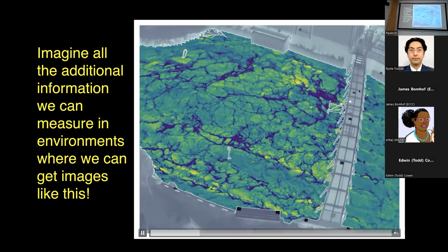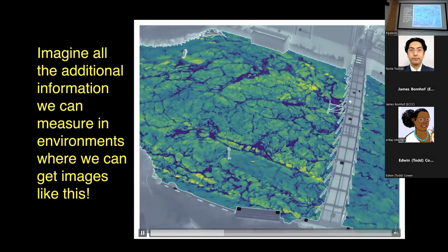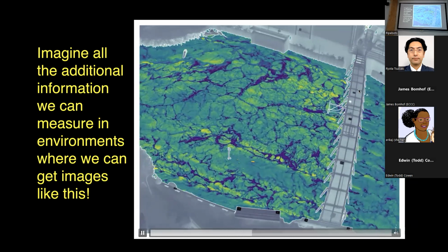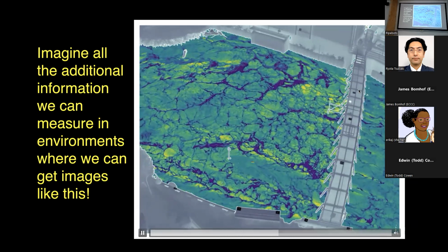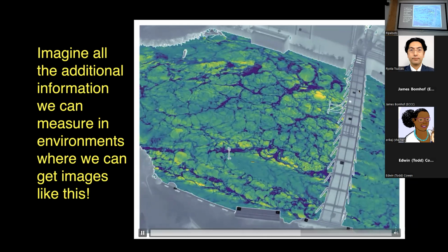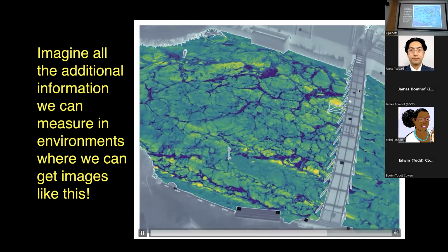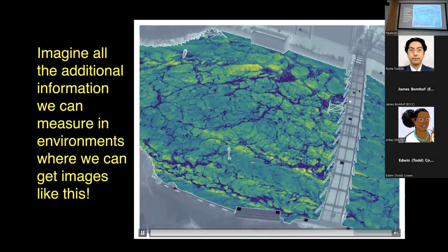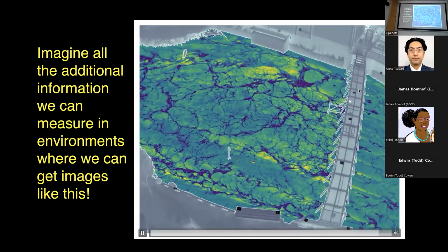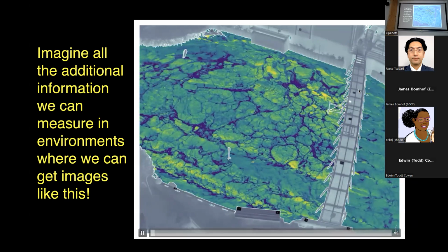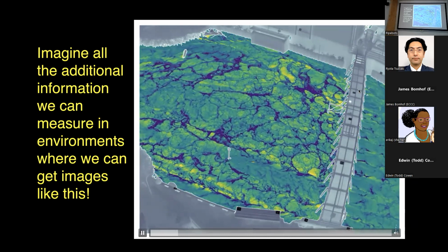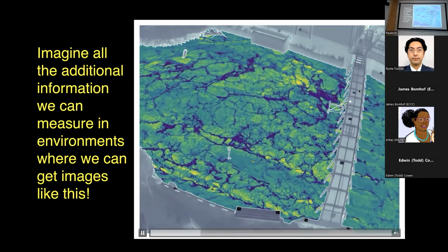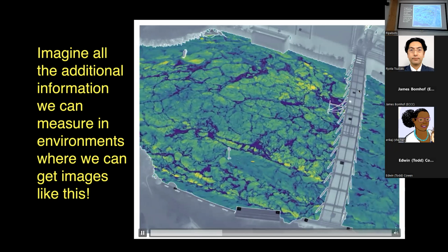One of the key models for gas transfer is what's known as the thin film model. As I'm sure you're all aware, the surface boundary layer is really, really thin on a free surface. We don't have the no-slip boundary condition. We have the dynamic free surface boundary condition and the kinematic condition. The eddies are splatting because of the kinematic condition, and the dynamic free surface boundary condition leads to straining of it.